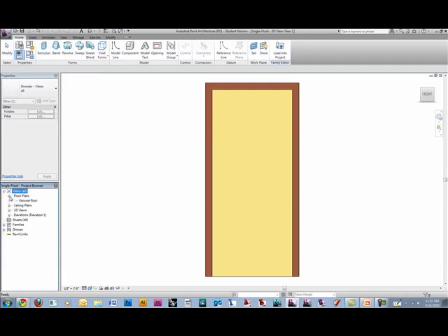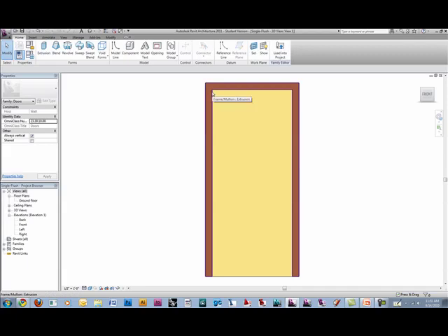It doesn't work as intuitively as the 3D massing environment, the conceptual massing environment, which essentially just came out with the 2010 and 2011 release. So before then, this was the only type of massing you had for creating forms. So it works a little bit differently than your project environment and differently from your conceptual massing. So it's a whole new interface almost. So keep that in mind when you're trying to model stuff. You can't just draw a profile and then extrude it or anything like that. You have to choose the right tool first and then do it.